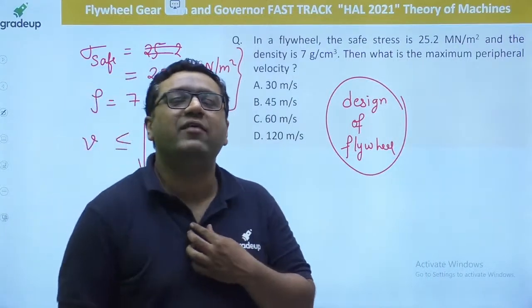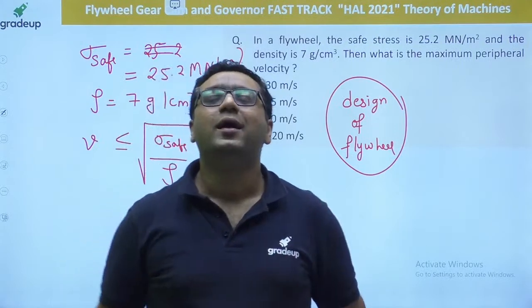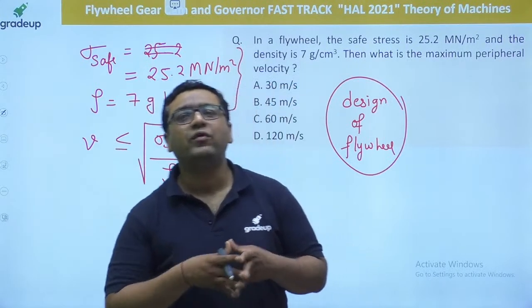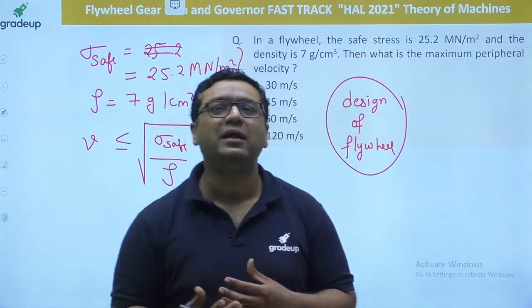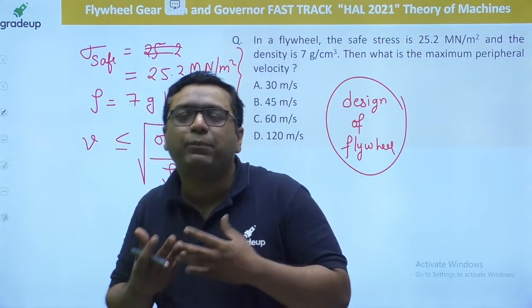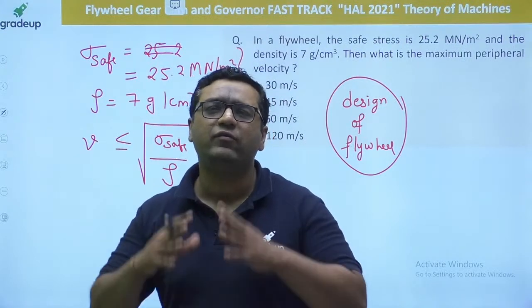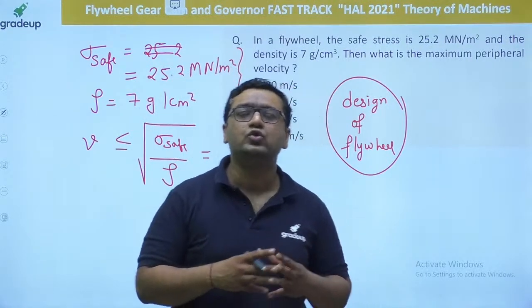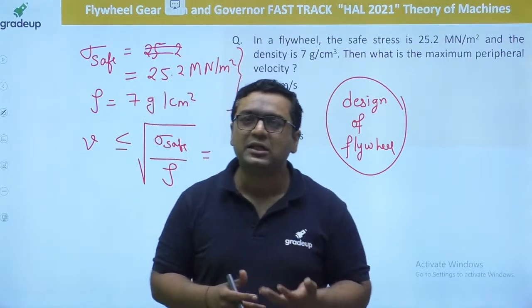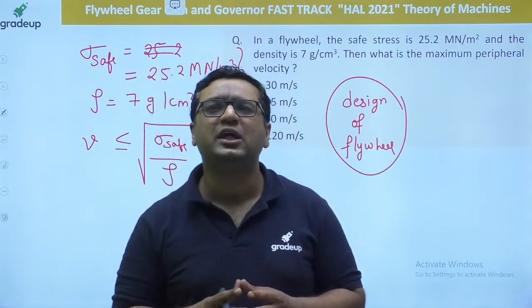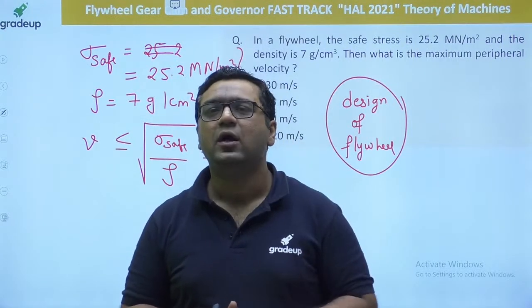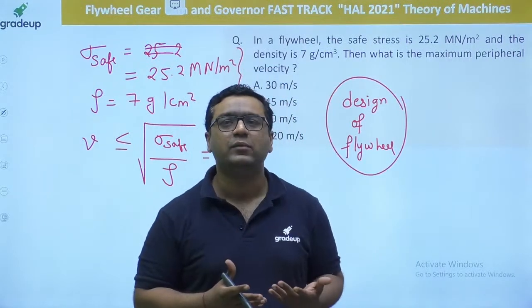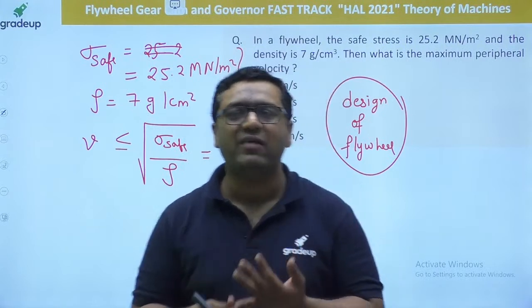Why is a flywheel not used in a gearbox? Dear, basically a flywheel is used in general when we have a requirement for storing and supplying energy, when we want energy at some particular interval. Like whenever you use the punching machine, energy is required only at the time of punching. For the complete cycle time, energy is not required except punching time. That is why a flywheel is required.